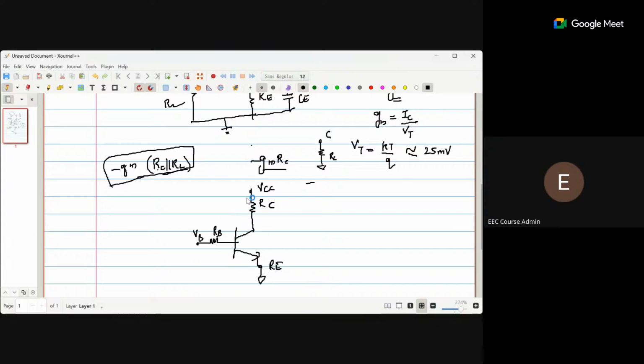Okay, so in that understanding, if you see this particular circuit as such, while you make it in the lab, you have to use one power supply for this VB and another for VCC. Since VB will be less than VCC, this VB value can be extracted from VCC itself by putting a voltage divider.